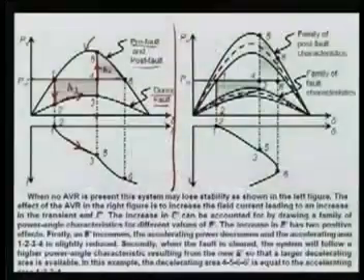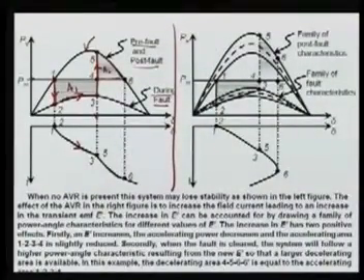You can understand what is happening from 5 to 6: your angle is increasing, but the machine is retarding, decelerating because the PE is more than PM. Meaning you are taking more power than you are feeding. So the machine will try to retard, but still it is more than synchronous speed. So it will come here at 0.6, and still a lot of kinetic energy is stored and it is not released. That energy which was stored here is not released, meaning this area is less than this.